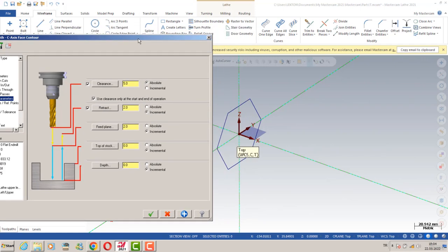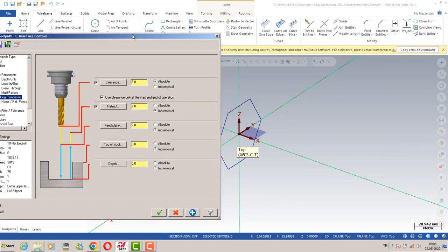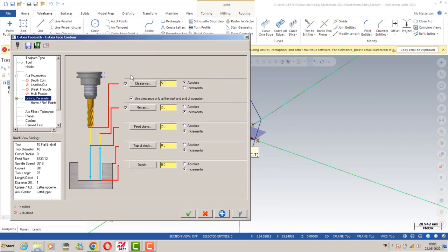But if you intend to use the wireframe position or the Mastercam axis position, you need to be careful about the absolute and incremental option. I'm also going to mention that. This is quite important. You can also see some examples. Okay, so this is my clearance plane, by the way. You can also see my options here. This is my retract position. For example, we are working somewhere, and then we're going to focus on the difference. So we're going to use the retract position, and then we can organize it as a 3.